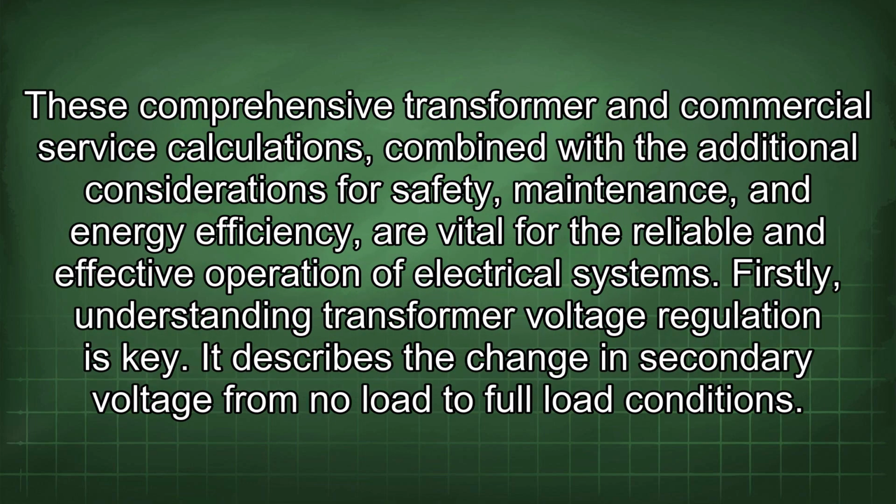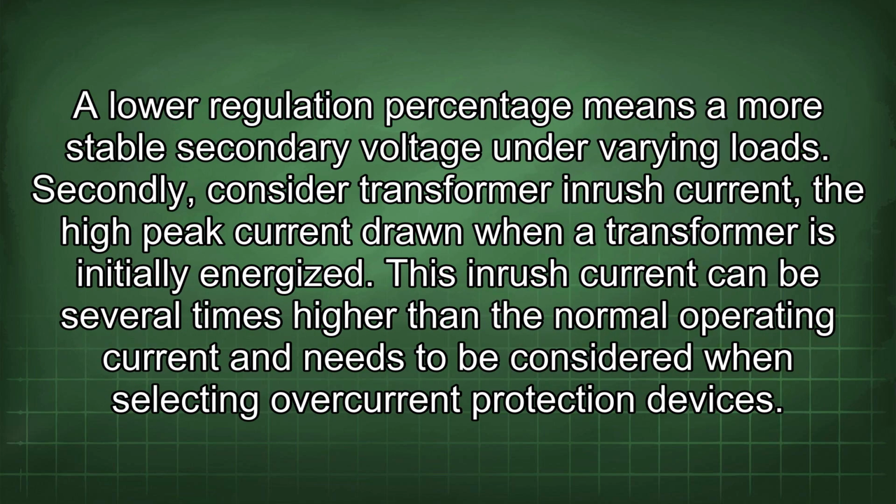These comprehensive transformer and commercial service calculations, combined with the additional considerations for safety, maintenance, and energy efficiency, are vital for the reliable and effective operation of electrical systems. Firstly, understanding transformer voltage regulation is key. It describes the change in secondary voltage from no load to full load conditions. A lower regulation percentage means a more stable secondary voltage under varying loads.